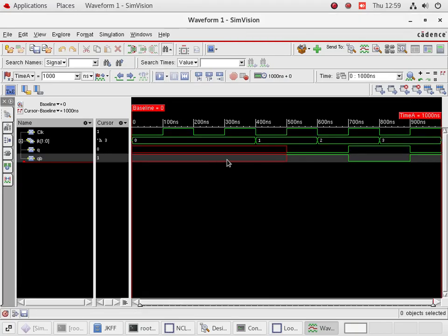So here you can see initially the value is not defined. You can define any values here. So then for 0 the previous state is retained, the value is not defined here. For 0 1 it is 0, for 1 0 it is 1, output is 1, and when the bits are 1 and 1 the output is toggled.